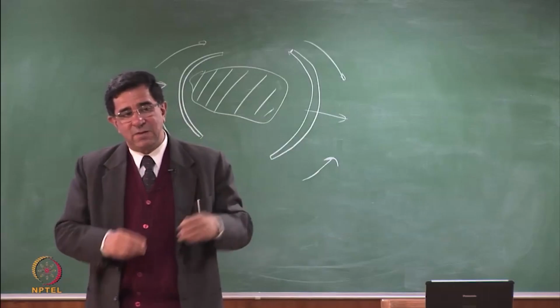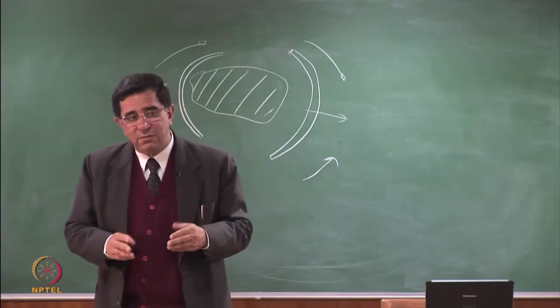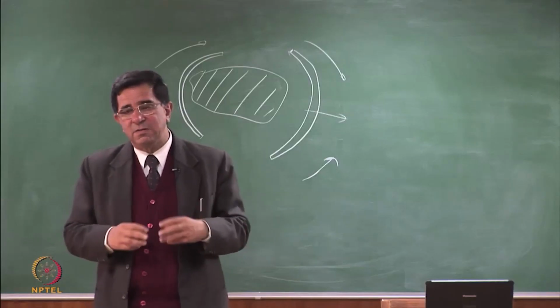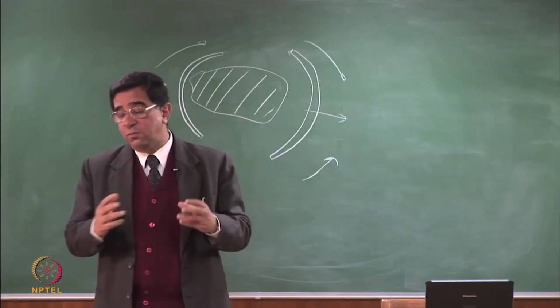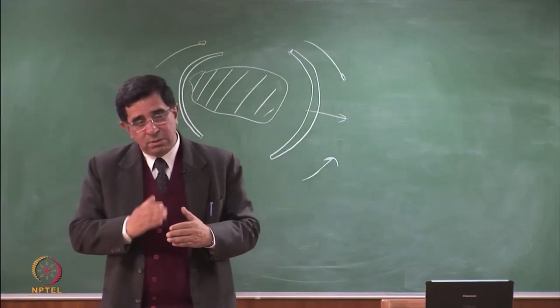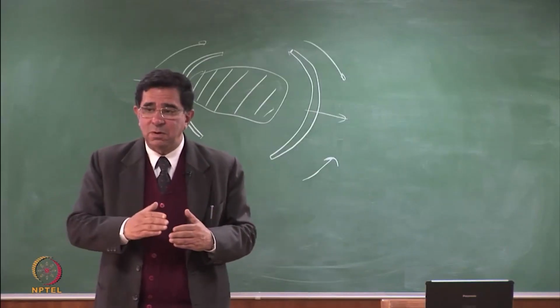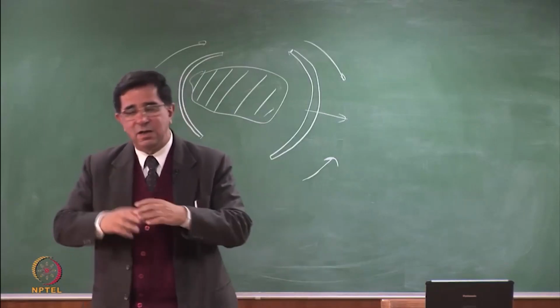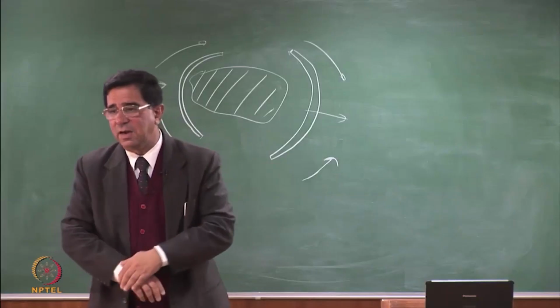And the second question is, if every year I am operating a phase of the landfill, are these independent phases or do we connect them? If I make them independent phases, I lose a lot of airspace. That means where I can put the waste. So when I put the next phase, it is integrated with the earlier phase, and therefore all the systems are also integrated. The cover is connected, the leachate collection system is connected, everything gets connected.